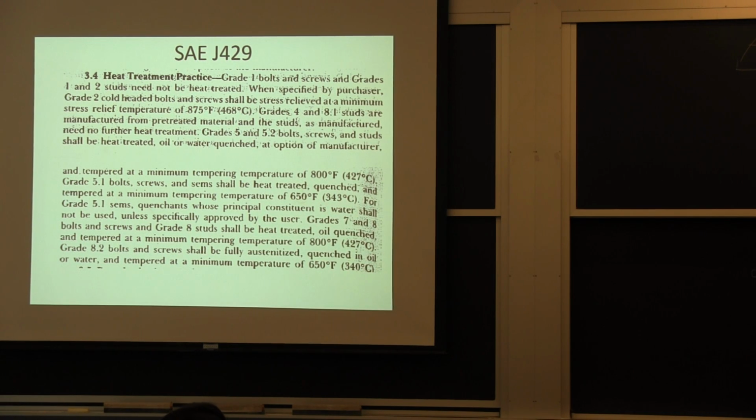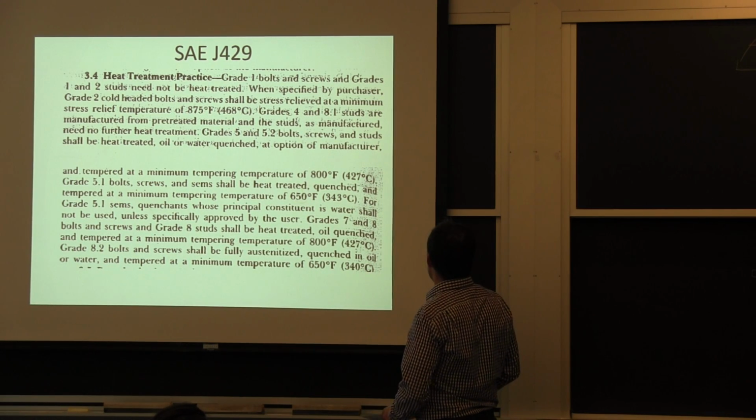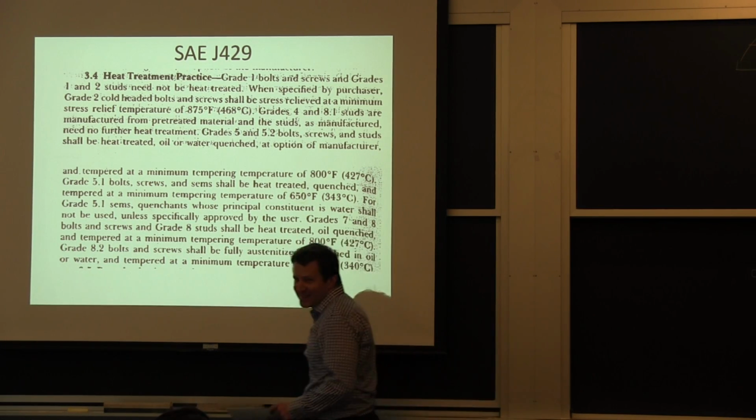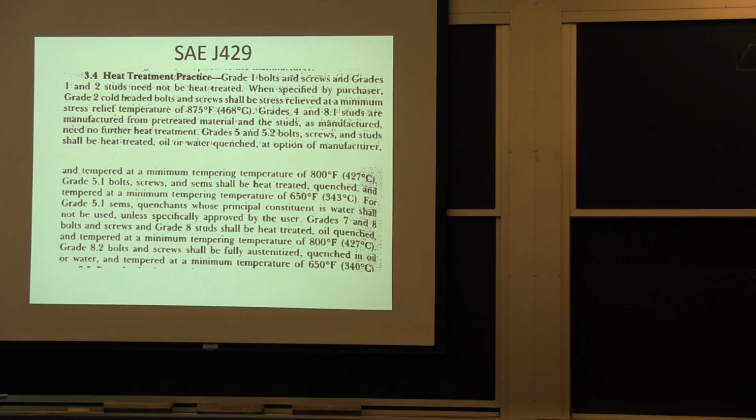So in that spec, there's this little paragraph on the heat treatment. I'm sorry if it's not perfect quality, but it's a copy I've been using for a while. It talks about, okay, you may need to do a stress relief if you have a kind of a general grade fastener, if you cold form the head.